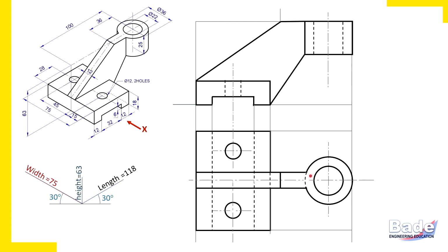This hidden line here is actually the base edge of the cylinder, the bottom edge of the cylinder, which is still there. Listen, at the top, the surface of the plate meets the surface of the cylinder tangentially, that is in one single plane. But the lower surface of this plate and the lower surface of the cylinder, they are not meeting tangentially. So this circular edge is intact, and its hidden portion we can see here.